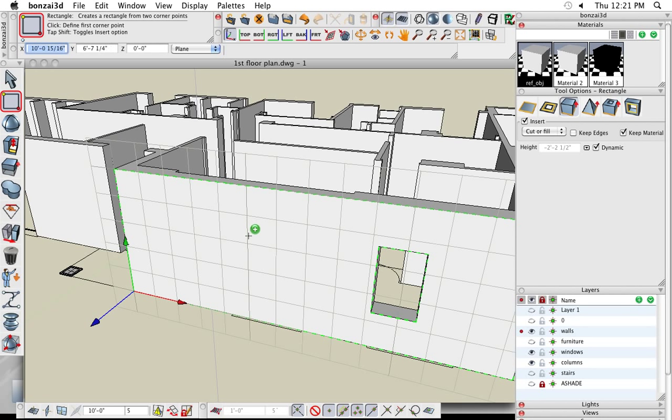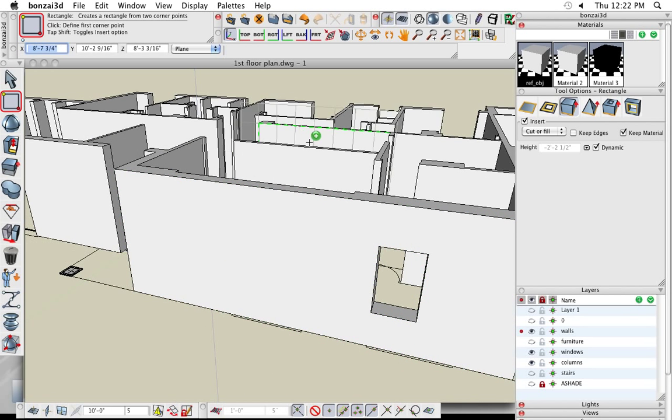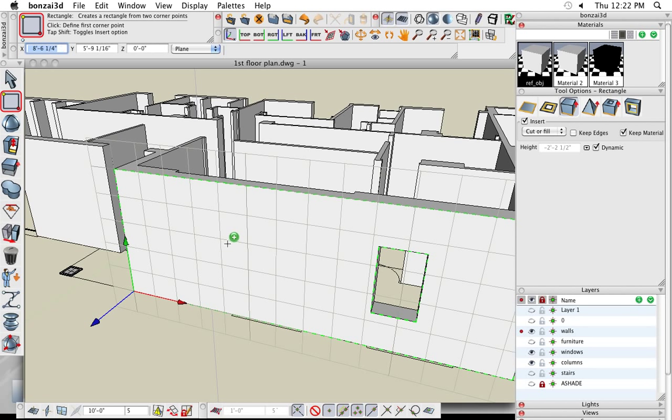Whenever I move the cursor, it moves the plane. If you tap and release the F5 key, it locks your drawing grid on that plane. So I can move the cursor anywhere that I want, and notice that that plane is locked. And the little lock symbol is down here. Press and release the F5 again. I sort of tap it, and the F5 key now releases so that now I can draw on any other grid. Now here's the second shortcut for you, the F4 key.